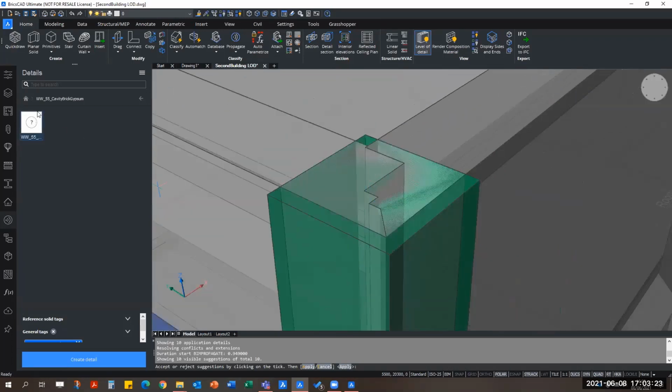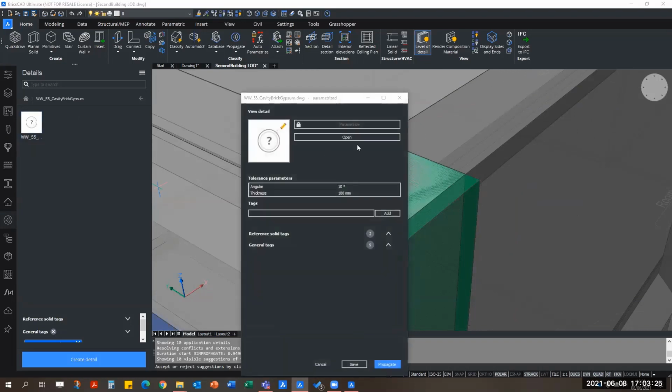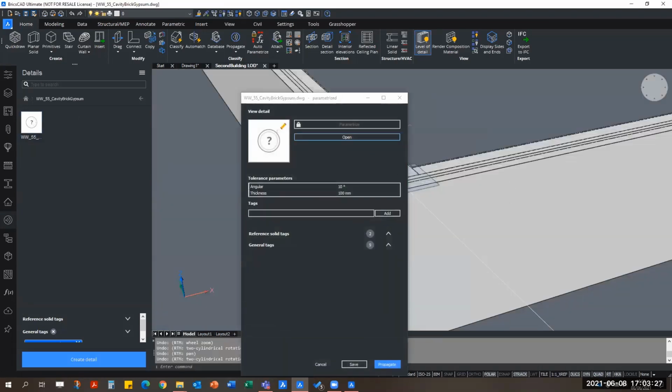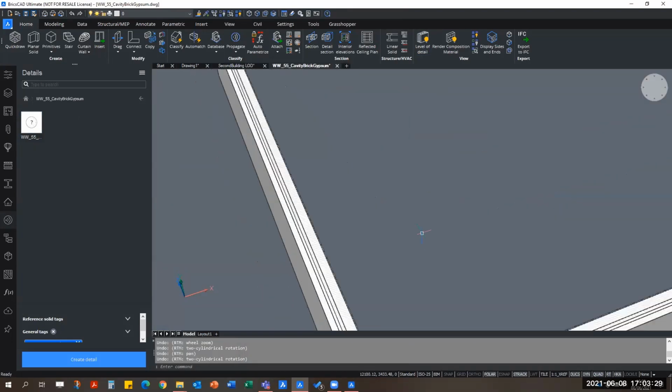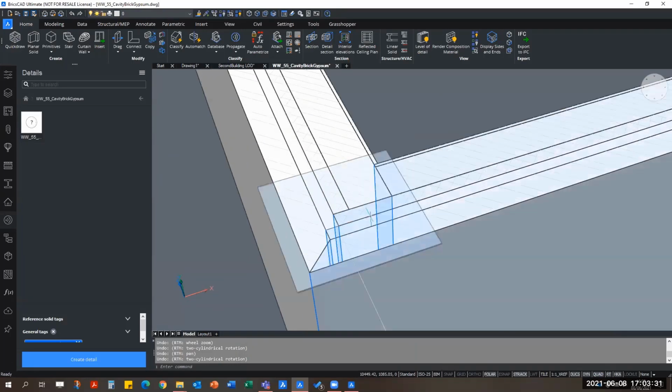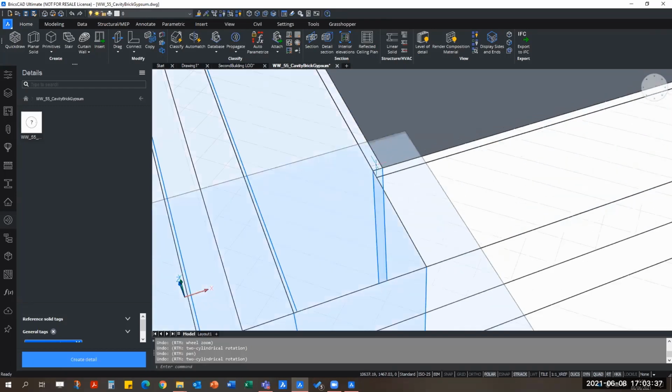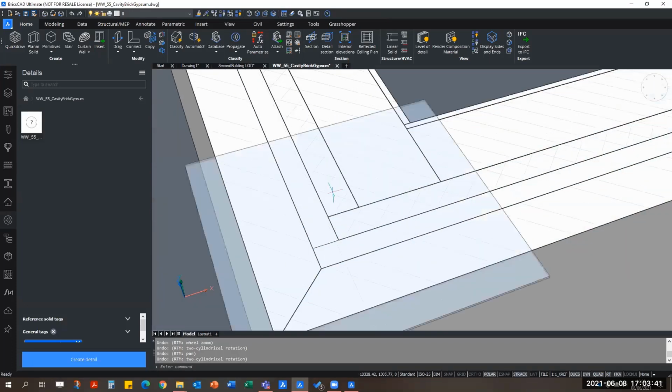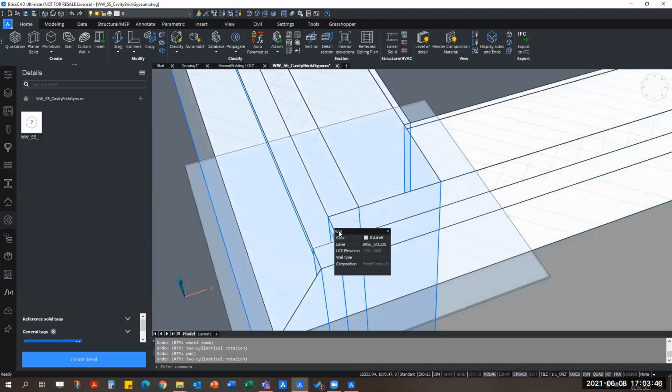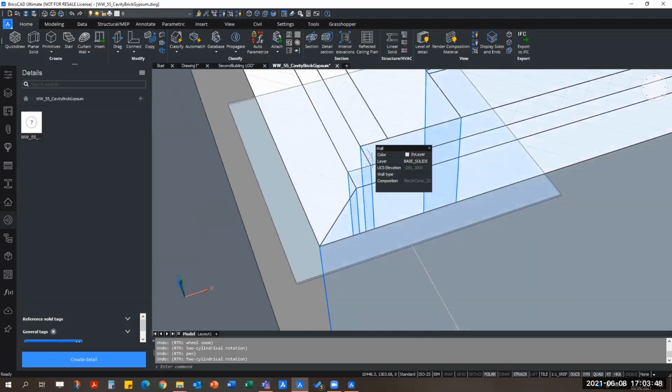So it's a detail that if I could actually open up, because now the thumbnail is not really working, it's a detail that basically helps, first of all, seal up the blockwork there, the gypsum plasterboard that's stacking like this, which is butting correctly, insulation that is stacking as well like this, rather than giving a miter joint, because that's not a really neat way to do.